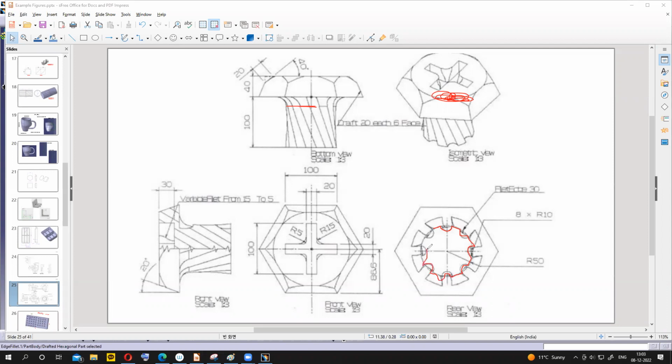Okay, the sketch, and copy that sketch to here. We create the sketch here, and copy the sketch to here, and use a multi-section solid with changing closing point on a different location. Okay, closing point for the sketch, suppose here. For the next sketch, closing point is in the other direction. Okay, and we use fillet here, edge fillet with radius